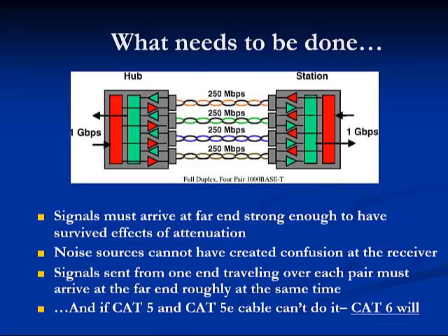Compare this transmission scheme with slower Ethernet networks such as 10BASE-T and 100BASE-T that use only two wire pairs and transmission in one direction, or half duplex. So the four wire pairs are stretched much more when using gigabit networks, and they are much more susceptible to performance-lowering electrical phenomena.